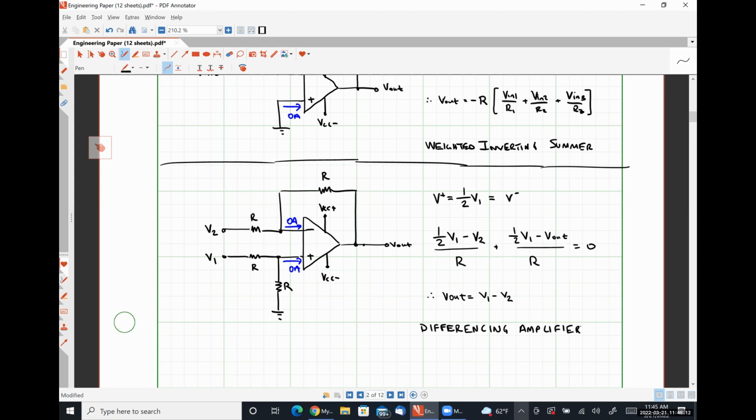So having equal resistors makes sense here because we're scaling by 1/2 and then scaling by 2 to get our original signal to the output. And then this part just subtracts that from the output as well. But as soon as we start having non-equal resistor values, it starts getting real wonky, real fast. Not saying you can't do it, but it's hard mathematically to choose things well to make it get a nice simple result. Sure. Why don't you do like 3V1 scale